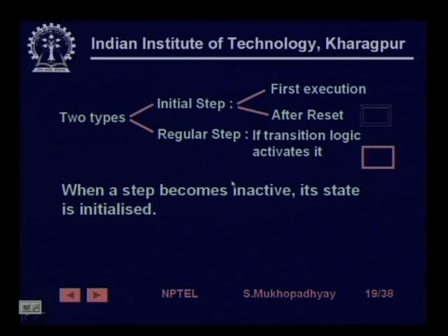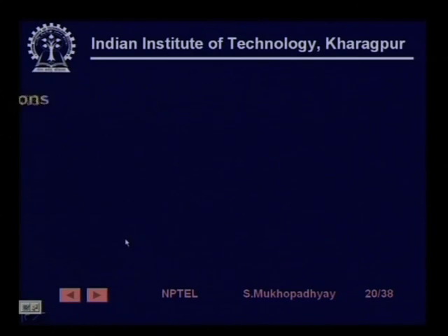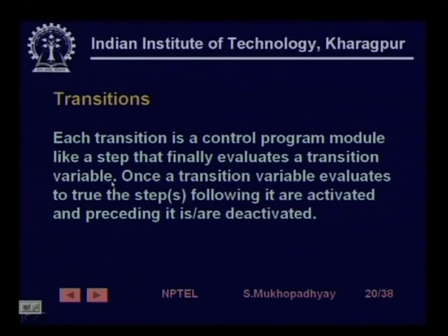So, when a step becomes inactive, its state is initialized, and only active steps are evaluated during the scan. That saves time. Now, we have transitions. Each transition is also a control program module which evaluates, based on available signals, operator inputs, etc., which transition conditions are getting enabled.